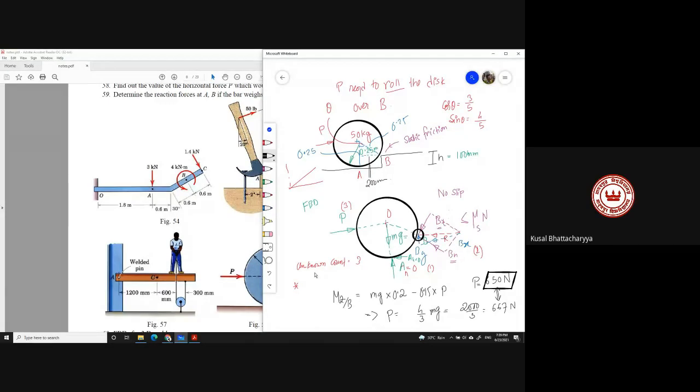Yes, the basic idea is correct, but you must put them in the free body diagram. Then after putting them in the free body diagram, mention that these quantities are zero, do that for an and at, because that is logically zero. That is the assumption that you have to make, without which you cannot solve the problem.